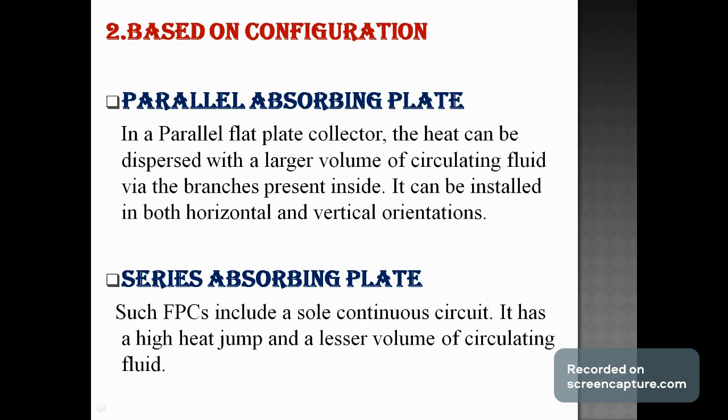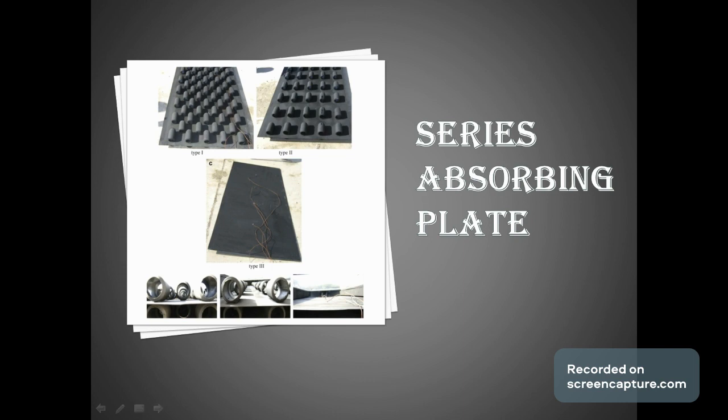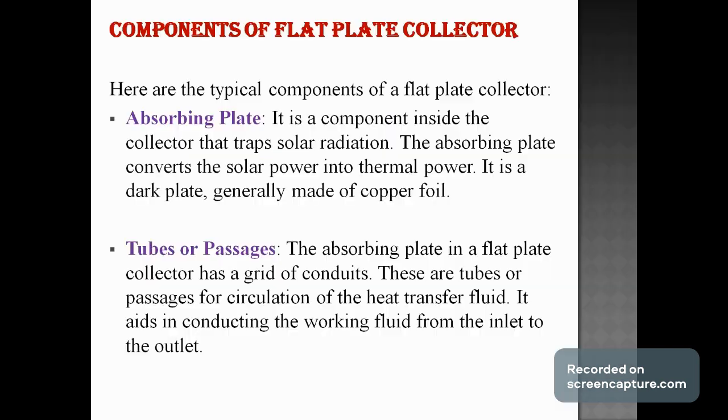And the next one is the series absorbing plate. A series absorbing plate FPC includes a sole continuous circuit. It has a high head loss and a lesser volume of circulating fluid. And this is the picture of the series absorbing plate.